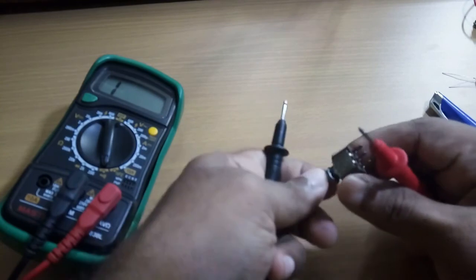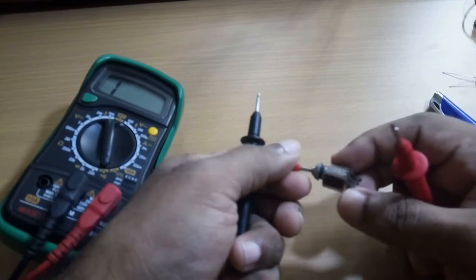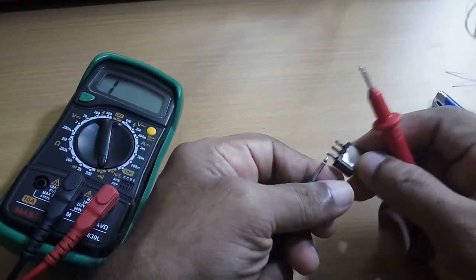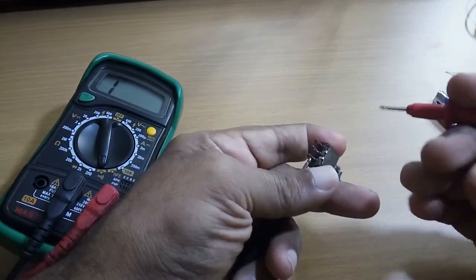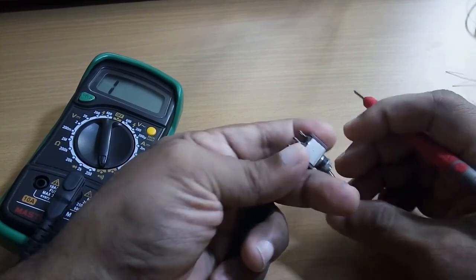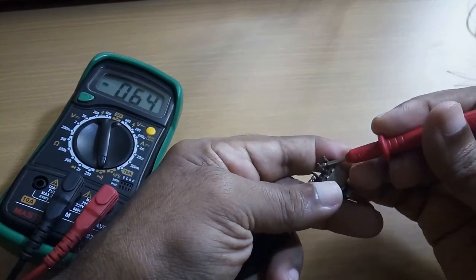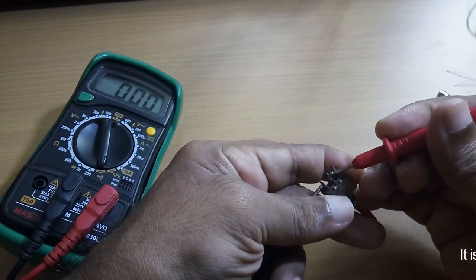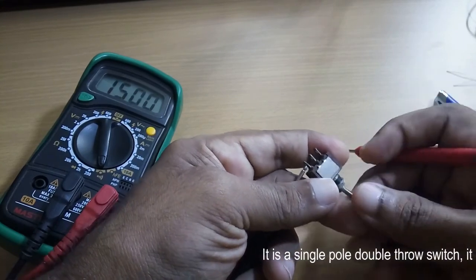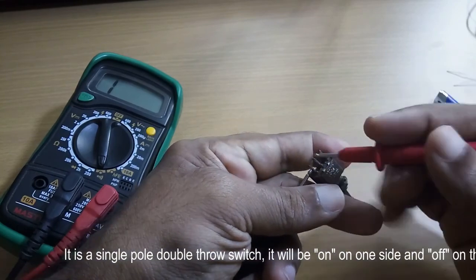Here we have a switch, a single pole double throw type of switch, and similarly we'll connect this and check whether the switch is operating normally. It should conduct in one position when you turn it in one direction, and on the other side it should not show any conductivity.